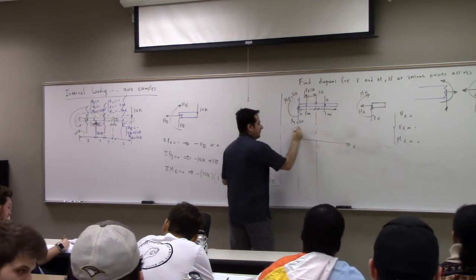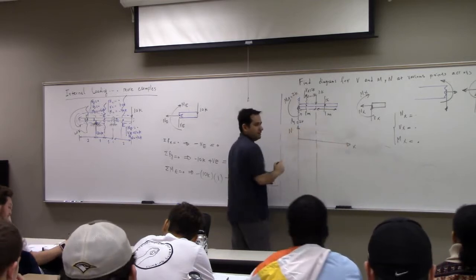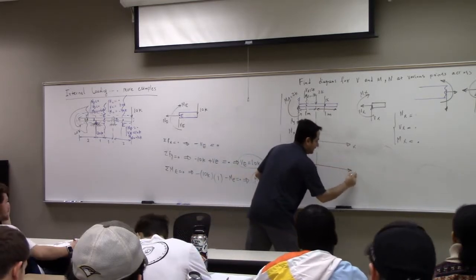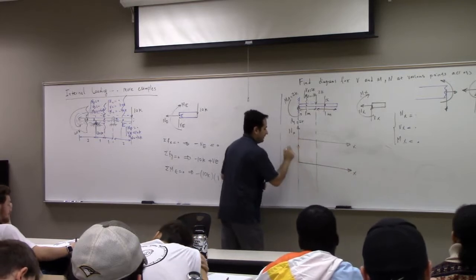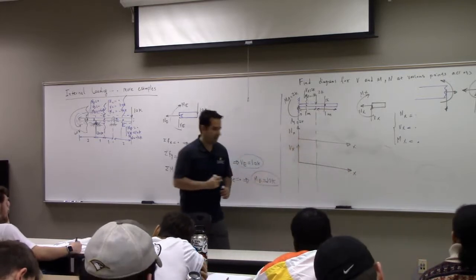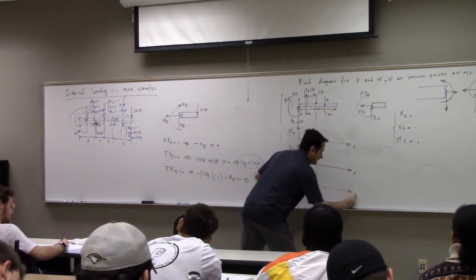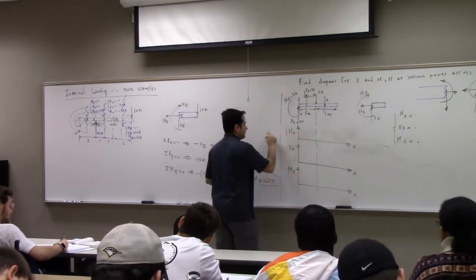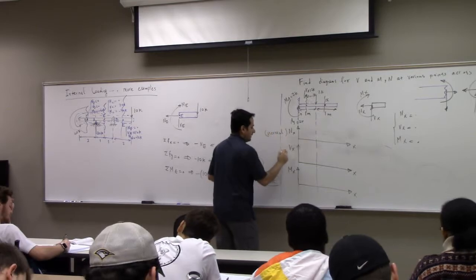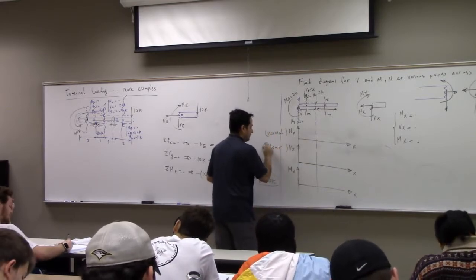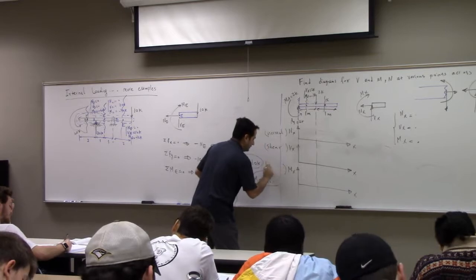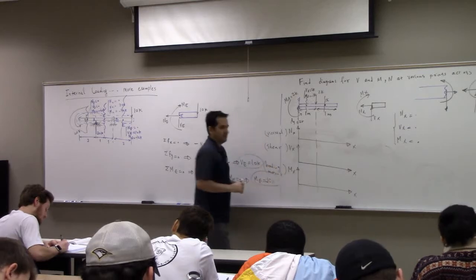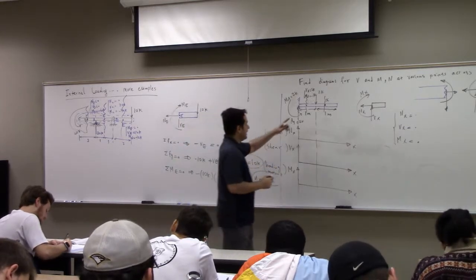So right now we want to guesstimate it. Let's say the y-axis in this diagram is N, the normal force at point x. Now I have another diagram, x, and the y-axis here is V, the shear load at x. And then I have another one at x, and the y-axis is the bending moment at x. So normal force diagram, shear diagram, and this one is the bending moment diagram, right?